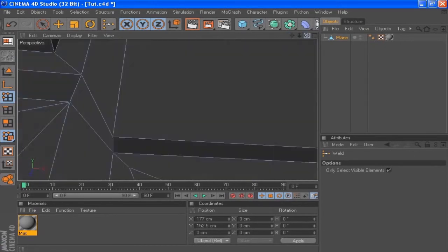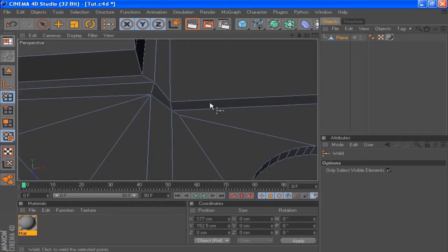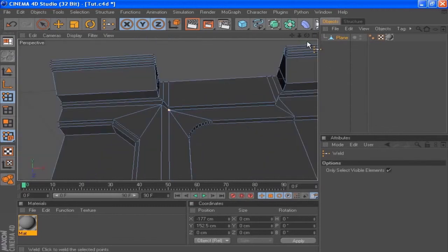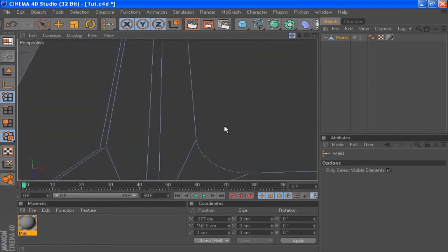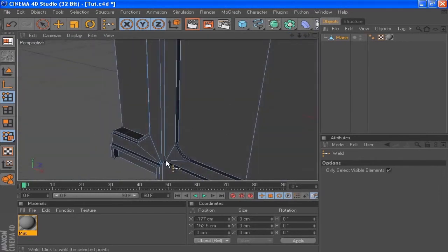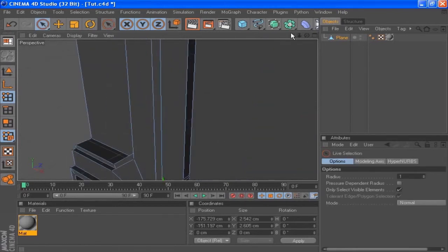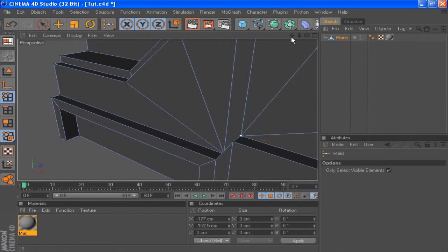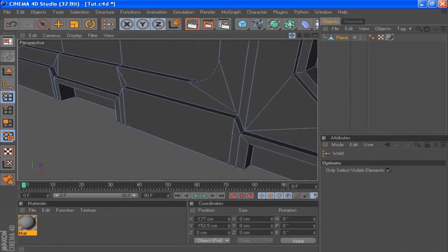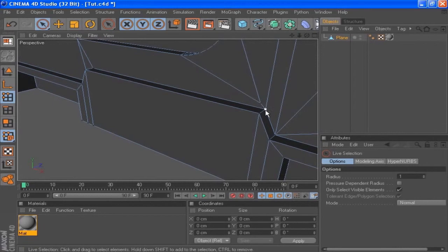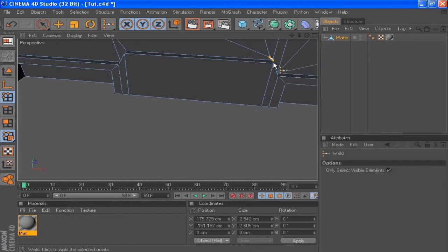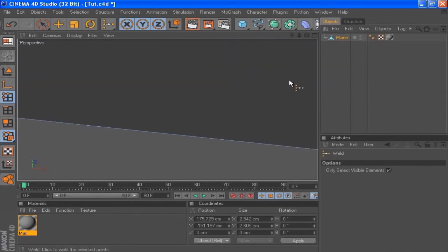Let's turn around, select this point, right click, weld, and weld it to the edge. Oops. Let's get close in so you know it's precisely done and we don't have any other problems. Okay, right click, weld, and then we gotta move to the side over here, and then select this point and this point. Oops. Is that right? Right click, oops, weld, choose weld and weld it. Let's get close so we can weld it properly. And we want to weld it over here.